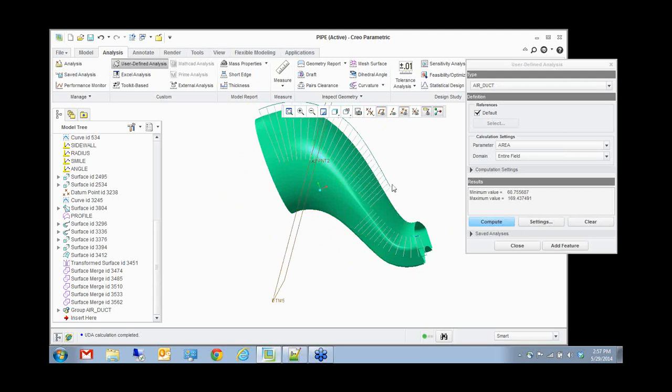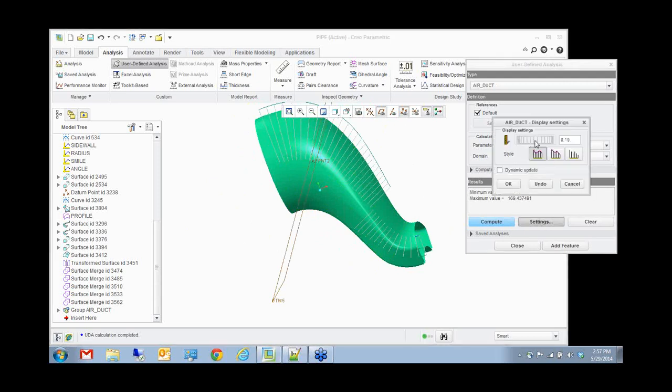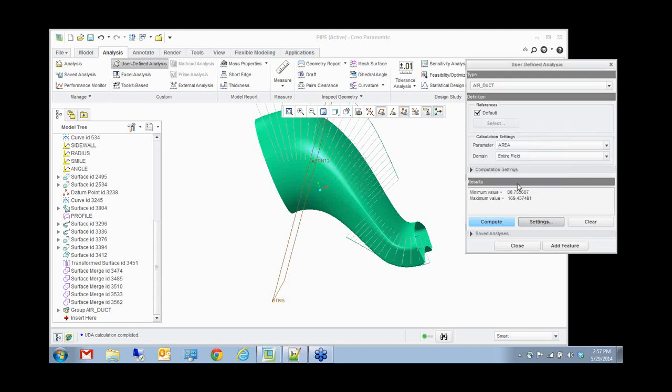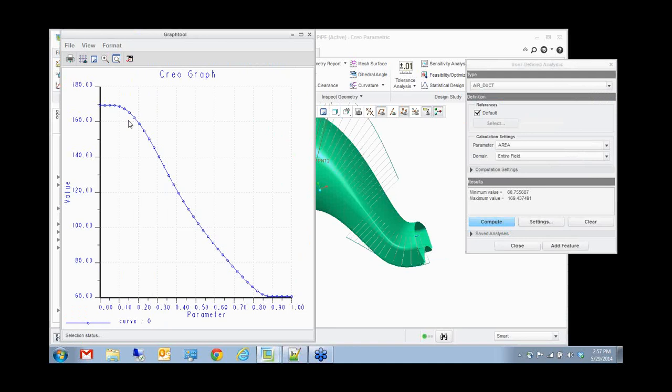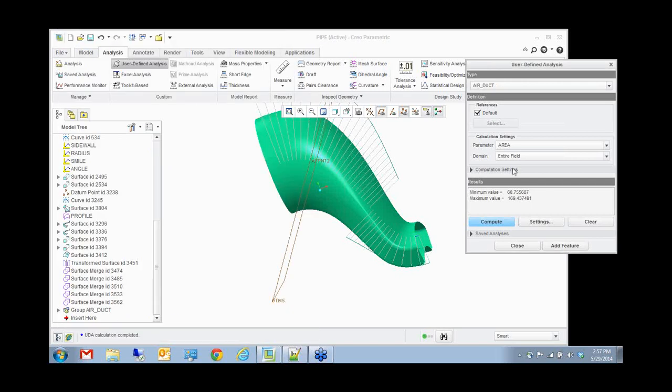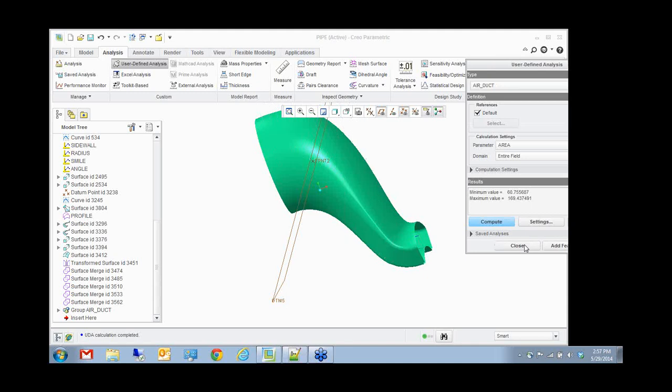If that graph is not smooth, or if these curve settings are not smooth, you can see right here, you can scale them and do some other things with it. See that? You can scale, and you can see if the graph is smooth or not. In compute, this gives you how your cross-sectional area is changing along the length of that particular pipe. Okay. Now this could be very important input into, say, some flow calculations.